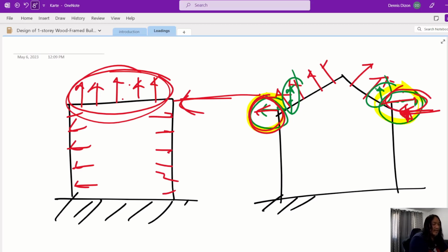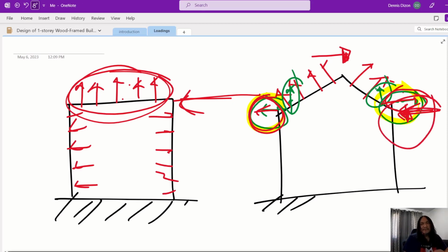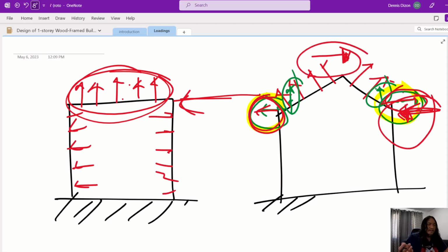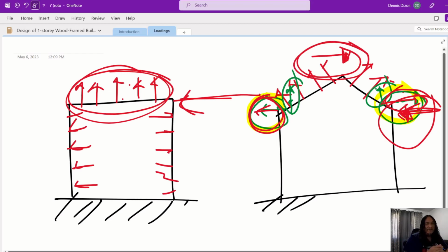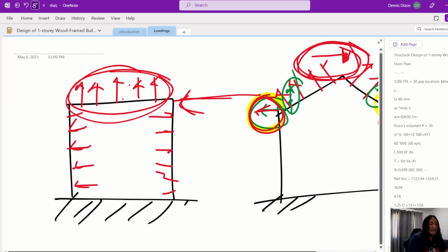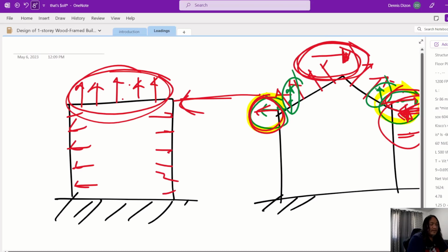So if you sum up these two, you have a negative net wind force going in that direction, which is opposite to your wind force direction. This one is going to the left. Now, what will happen? This one will technically be reduced because of this net wind force. But we are designing for a worst case condition, and we don't want this. Technically, this is how it should be done, but in my practice, I'll just completely neglect that one. I will just use this wind value.